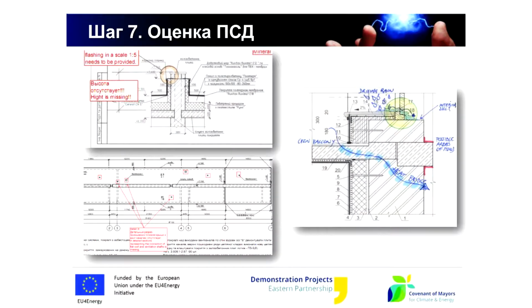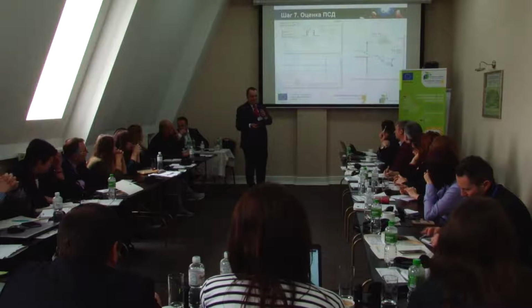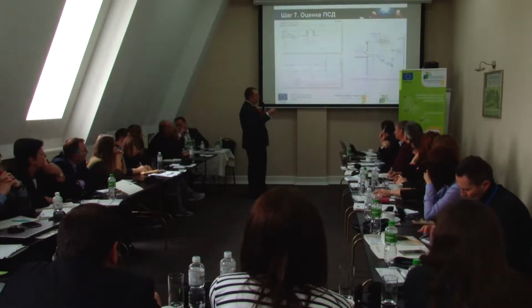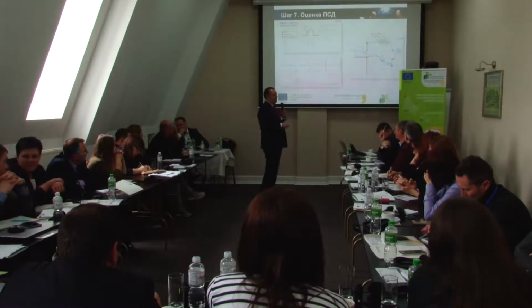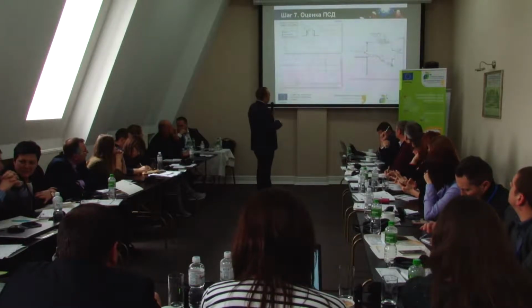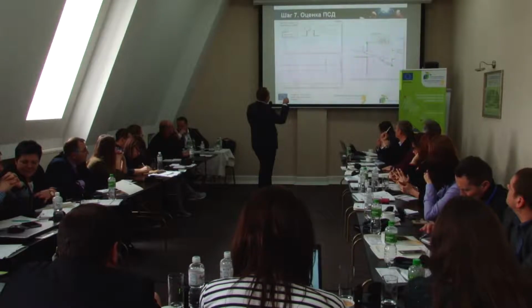For instance, here they remark that this part of the balcony is not insulated, therefore they reach a heat or cold bridge, so they recommend to correct things here. So they really try to do everything possible for the designer, developer to change these in order to avoid such negative situations, even already at the stage of developing design.